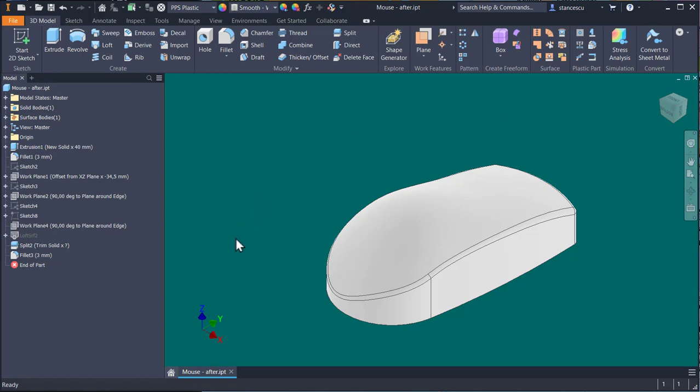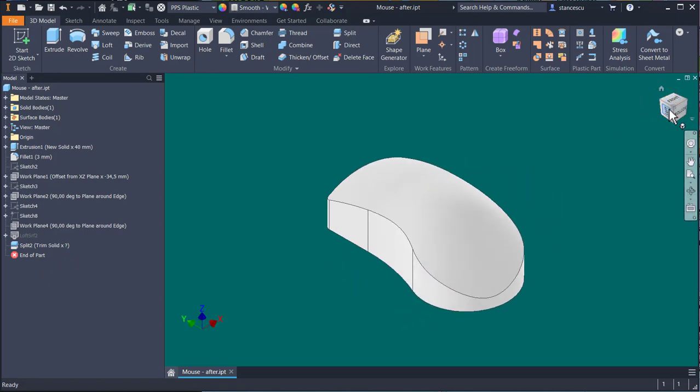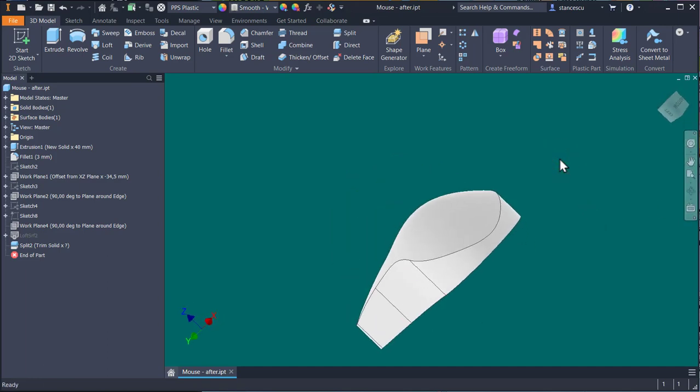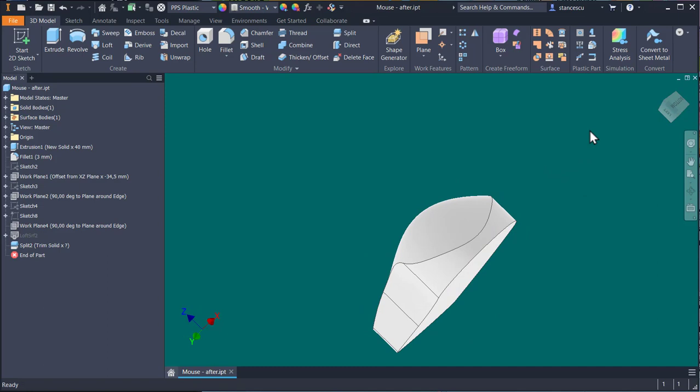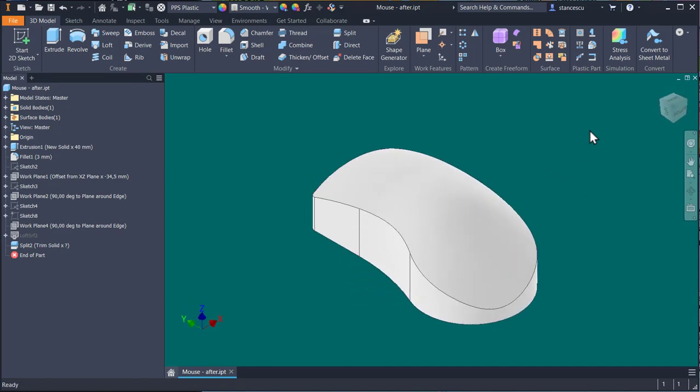The first thing I do is to eliminate or suppress this fillet. I delete it to have no problems. Firstly, I change the view to be this presentation. You know the procedure. Set current view as home, fit to view. And now, no matter where I am, if I apply F6, I have this presentation.